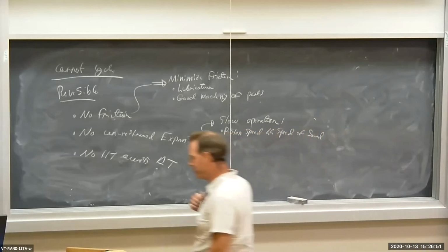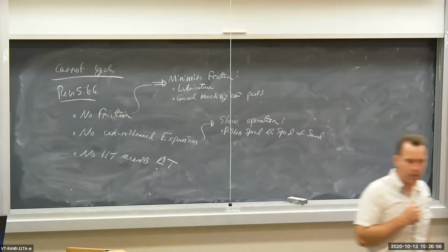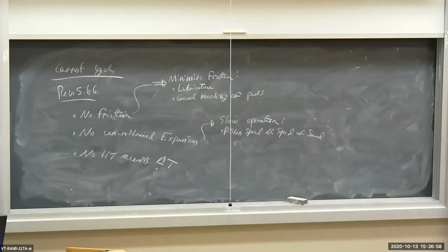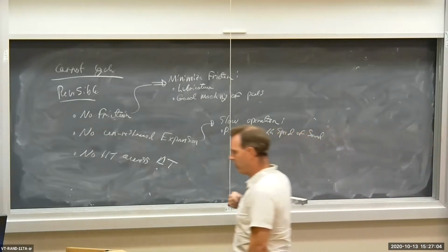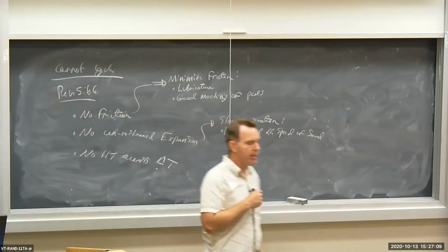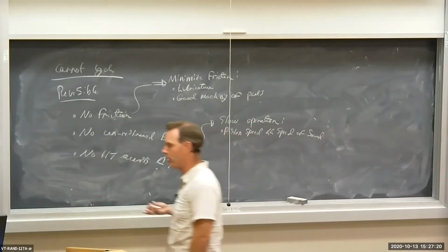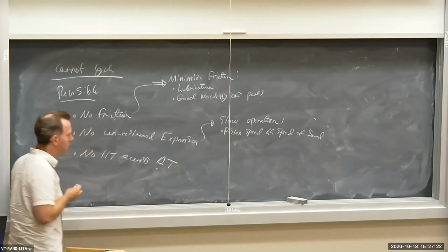unrestrained expansion. By the way, for those of you that are big diesel fans, you have a diesel truck, big diesels tend to turn or operate at a very low RPM. So that is one reason why diesels are very efficient. One possible reason why diesels are very efficient, they tend to turn very slowly, therefore minimizing unrestrained expansion. So that's one benefit of a slow turning, especially a slow turning diesel, okay?